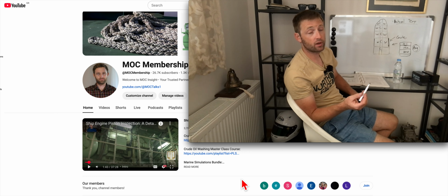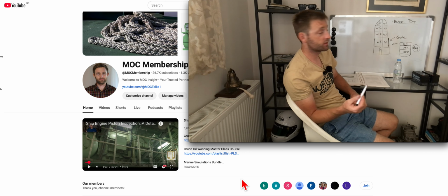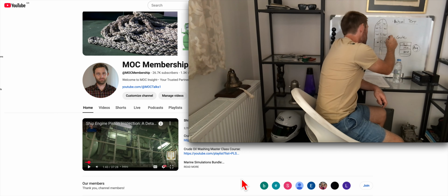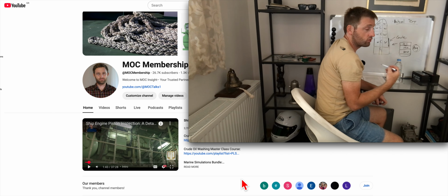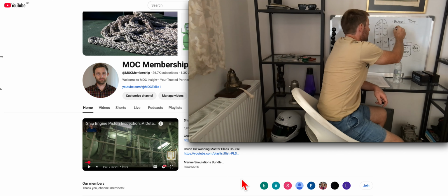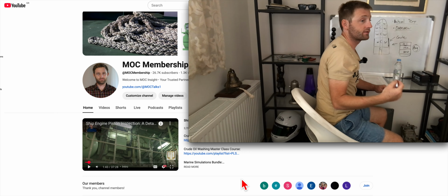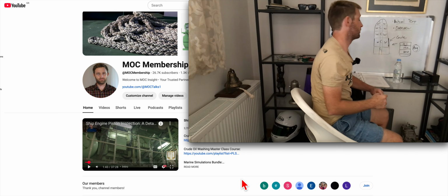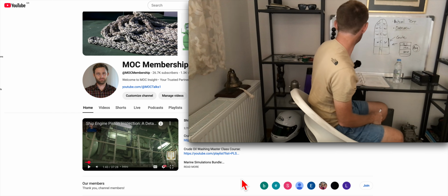Share it with the cargo surveyor or expediter in advance, and also make some measurements of the free water in the tanks, which will give you a much more accurate overview of the condition inside the tanks from the free water perspective.